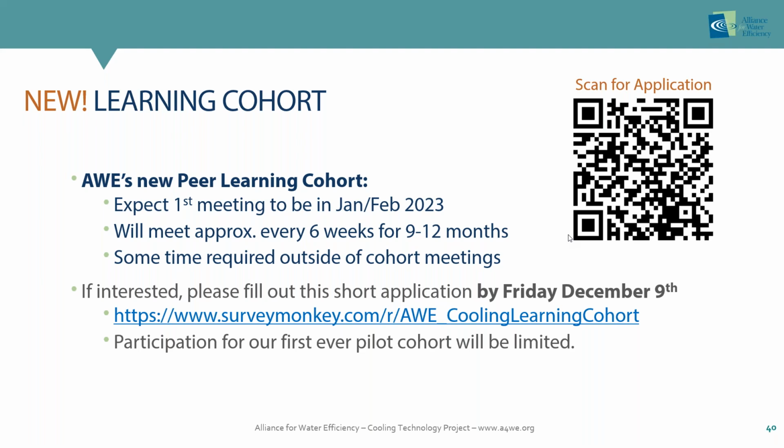It's going to be the last tab in CTEM, the CTEM water quality helper tab, that you can use or not use. It's optional, but it's something to explore the different constituents that might be present in your water source. Then it will help you understand how they may or may not limit the cycles of concentration potential, so you can better understand what's possible in your service area and what you might need to address from a water treatment perspective to improve water efficiency.